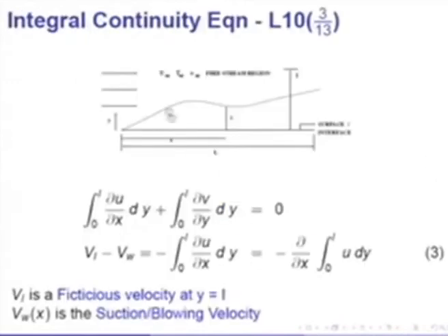This figure shows a surface on which a boundary layer grows. Of course, a boundary layer development can be uneven. The boundary layer can grow, then shrink and then grow depending on the pressure gradient that is applied. And when u infinity varies arbitrarily with x, of course, the boundary layer thickness too will vary arbitrarily with x. But we always choose to analyze a boundary layer over a given length L, and in this length L, we make sure that we choose a dimension L which is greater than delta max in this region as shown here.